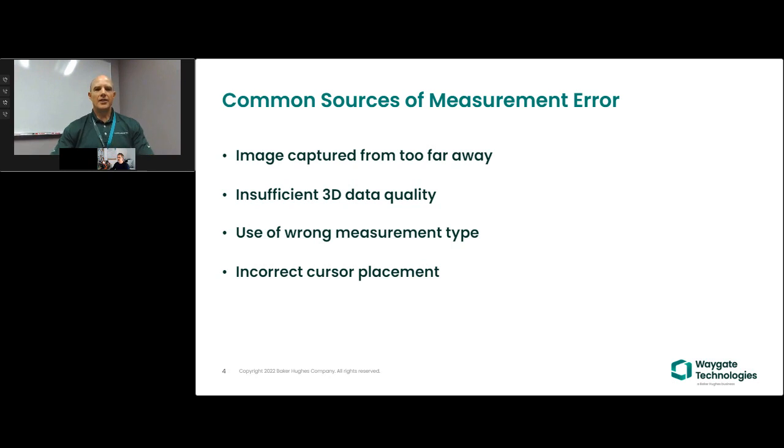Next, having insufficient 3D data quality for the measurement you're performing. This is especially true with small depth type measurements. It can be caused by capturing the image from too far away, but other factors like surface finish, glare, reflections, etc., can also degrade the quality from any distance.